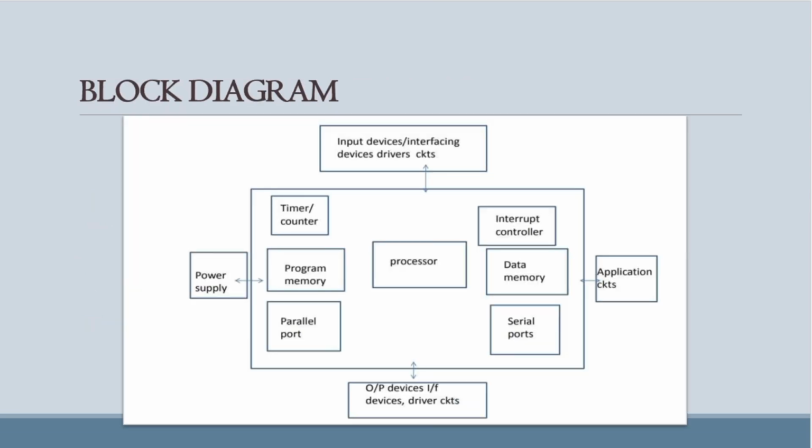And then, to go more deeply into this project, we should look into the block diagram which shows how different parts of the washing machine system are connected. Input switches are used to select modes or start the machine. Timer and reset manage the operation timing and allow restarting. The microcontroller which we used in this project, PIC16F877A, is the brain that controls everything.